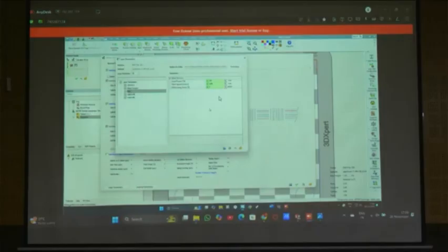No, no. What you are saying is related to design, the solid lattice versus solid porous, comparing in terms of design. But I am speaking from the printer point of view. First we need to fix the printer optimization parameters, and that is what we are doing. Once we optimize the parameters, then we can go for the design parameters.